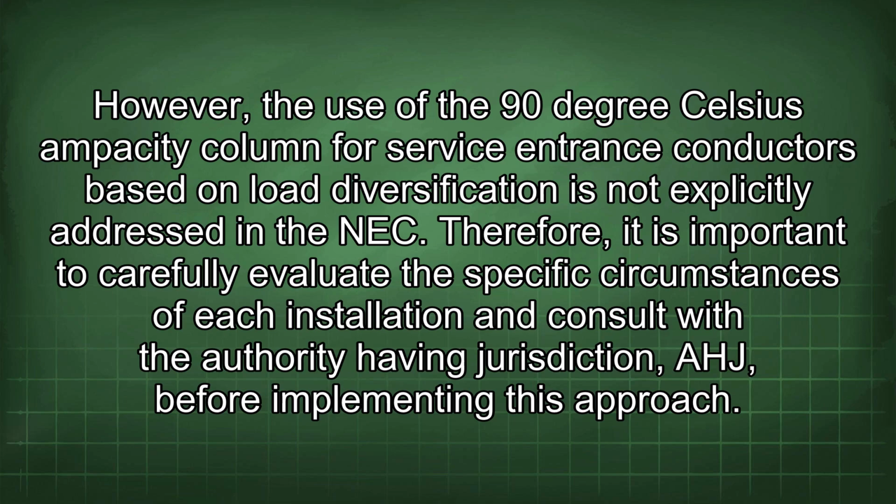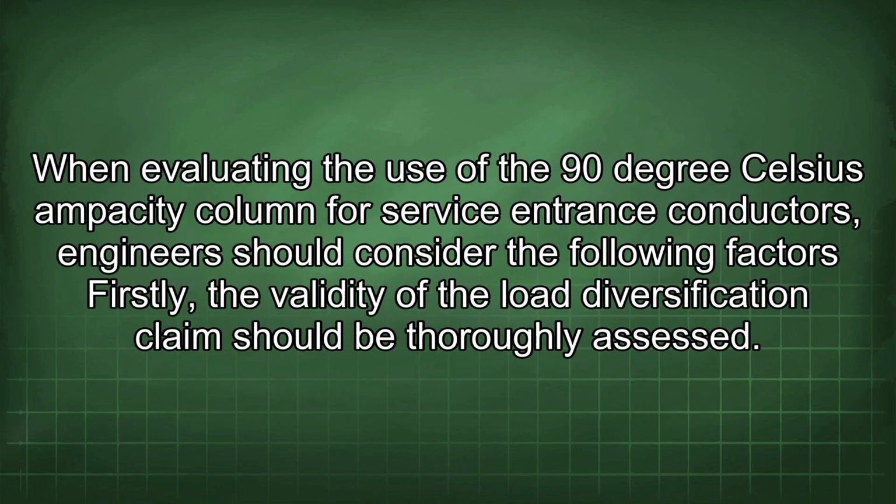Therefore, it is important to carefully evaluate the specific circumstances of each installation and consult with the authority having jurisdiction (AHJ) before implementing this approach. When evaluating the use of the 90°C ampacity column for service entrance conductors, engineers should consider the following factors.